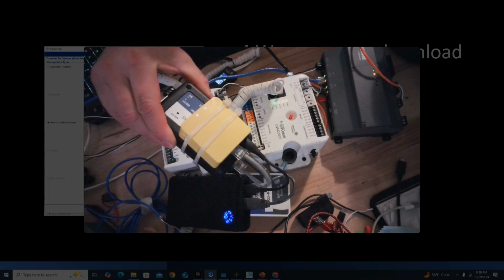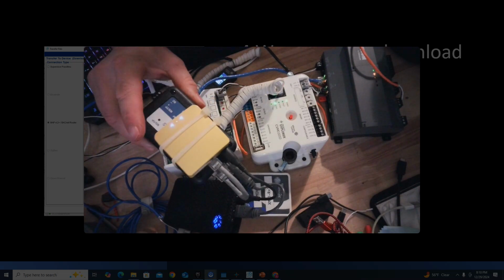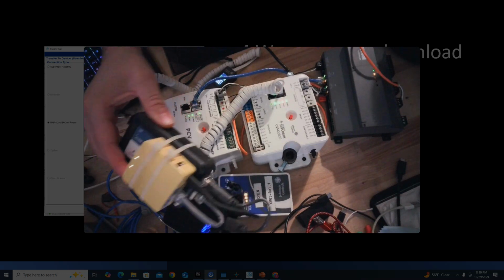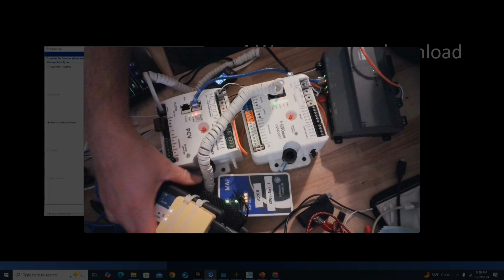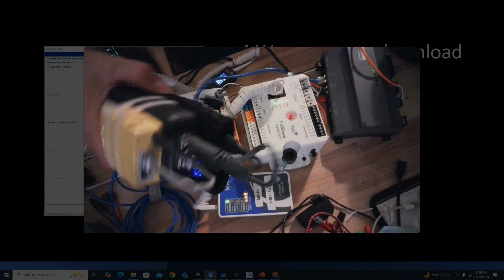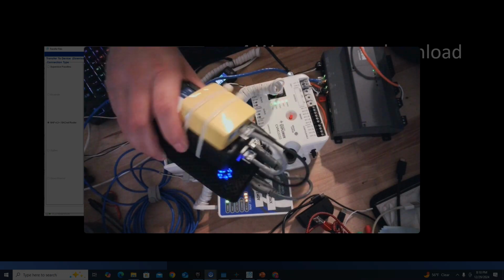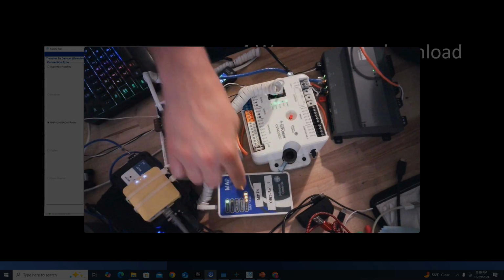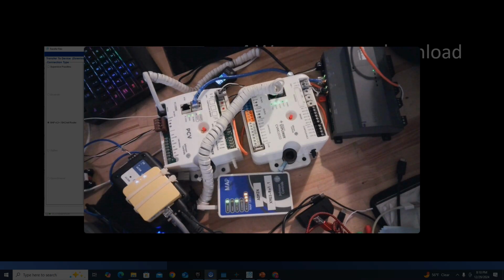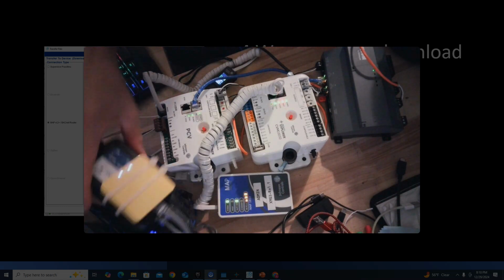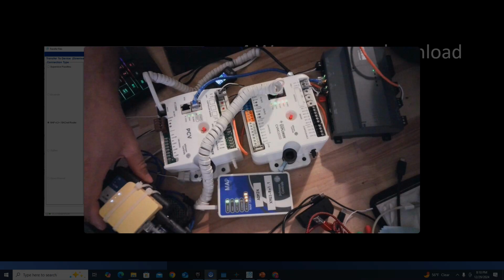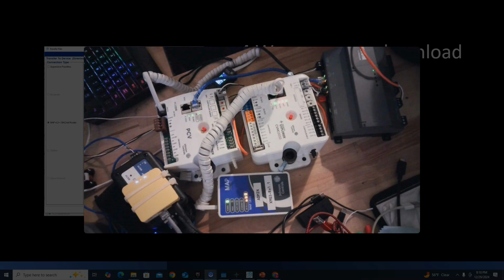I took a Contemporary Controls router and I meshed it with a little travel Wi-Fi router, and I made the whole system portable. So wireless, just like the Map Gateway and CWCVT tool, but this can be used on other vendors, not only Johnson Controls, so anything BACnet.